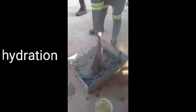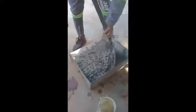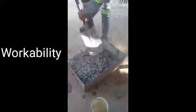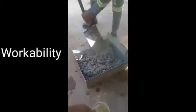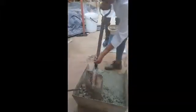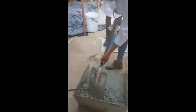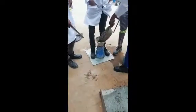And if concrete hardens, then it becomes difficult to mix, which will require a lot of energy, and that affects workability. Since it was hard to mix because water was little, then workability was affected in this group. A few moments later, the mixing was done and the practical was halfway to the end. A slump test was begun.